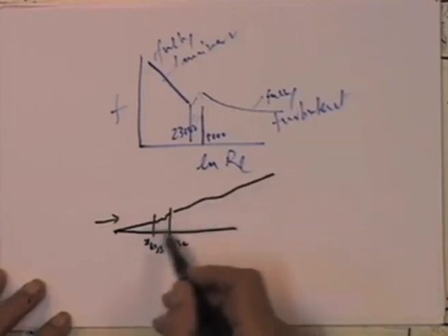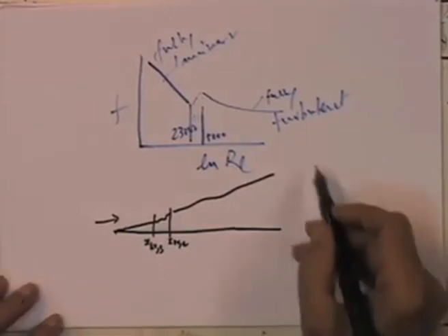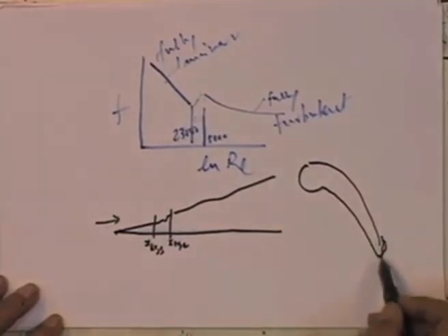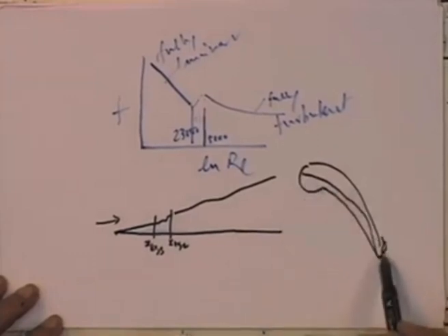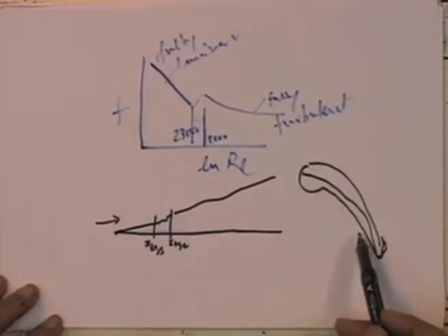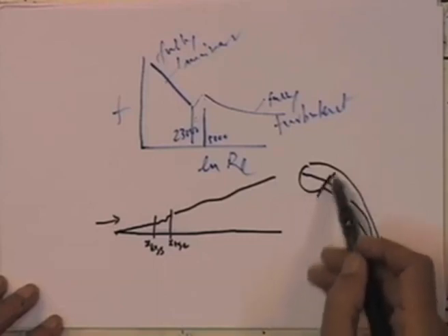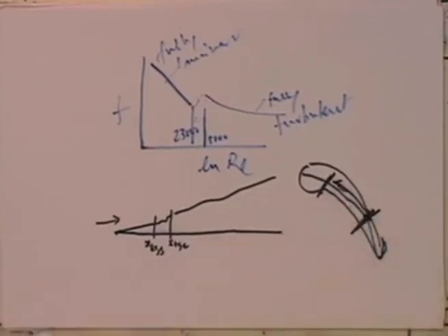So, this occupies a much smaller length of the total length of a boundary layer. But on a turbine blade, this is the chord length, and you could get transitional range occupying almost 50% of the chord length. So, that is why we need to study turbulence in a transitional region somewhat more carefully.